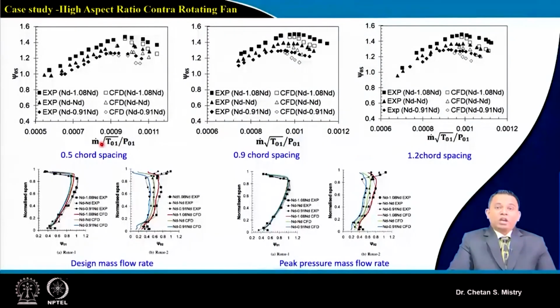But when we are doing our analysis or when we are making both the rotors, then what needs to be the axial spacing between these two rotors is very important. Basically that is what decides your aerodynamic performance, your expected noise as well as the length of your stage.